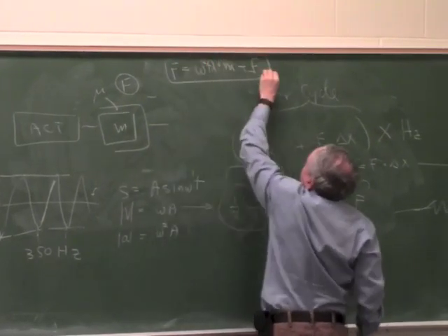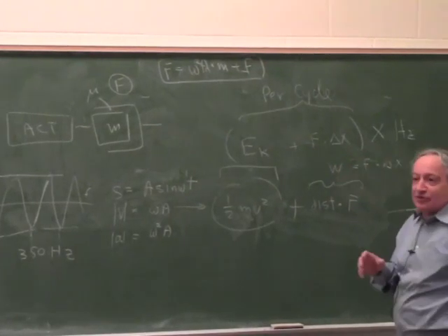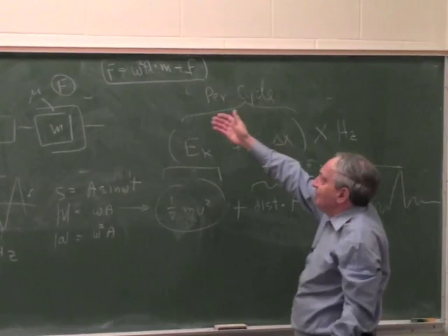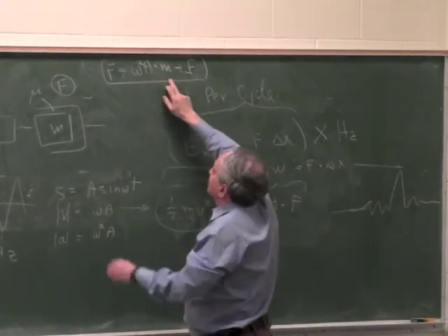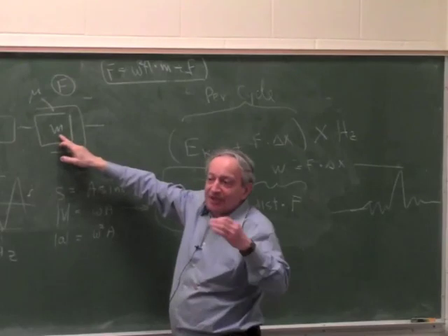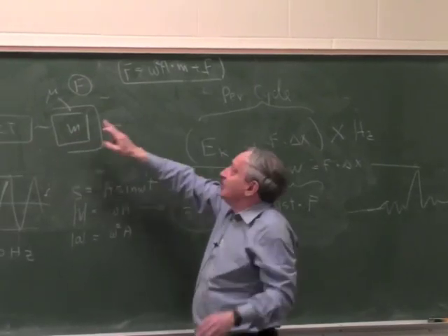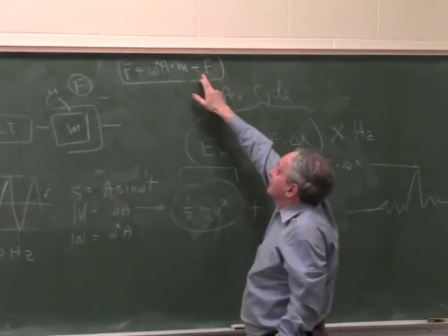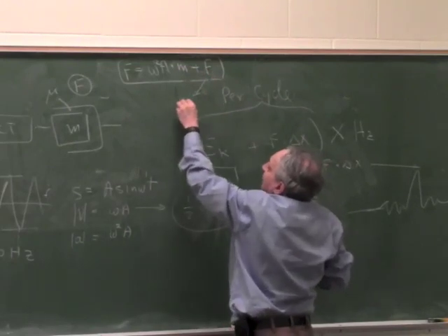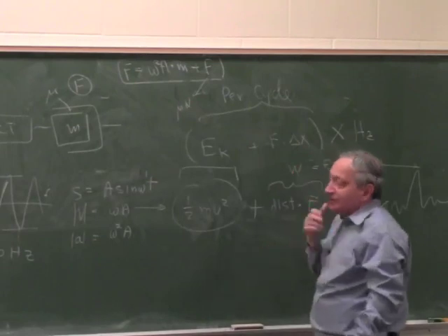So if you want to specify the actuator by force, not by power consumption or power output, it's even simpler. This is a force to accelerate the mass. It's a peak, a point of maximum acceleration, plus a constant force. And the constant force could be, for example, some mu n, some friction force, could be any other force.